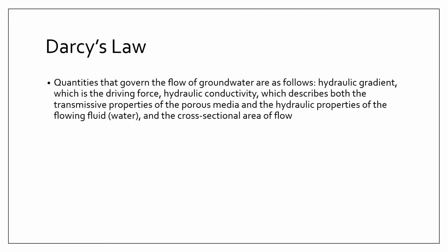Now, hydraulic gradient is all about the driving force. We're talking here about the change in potential energy of the flow, and the bigger the change in potential energy, the more driving force you have. The next is hydraulic conductivity, which is about the capacity of your aquifer, which could be soil or fractured rock, and its ability to transmit water.